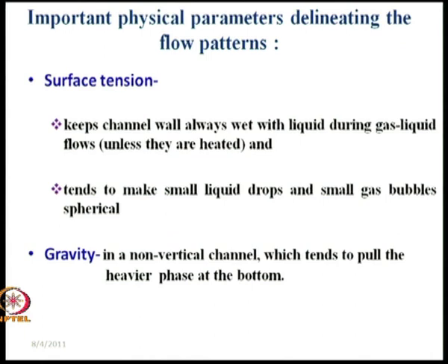Now, remember one thing, that for the first point which I have mentioned, there can be certain exceptions. For example, when the tube is heated and the wall temperature is much higher than the saturation temperature of the liquid, under that condition, vapors will be generated at the wall and they may try to stick to the wall up to a particular distance.